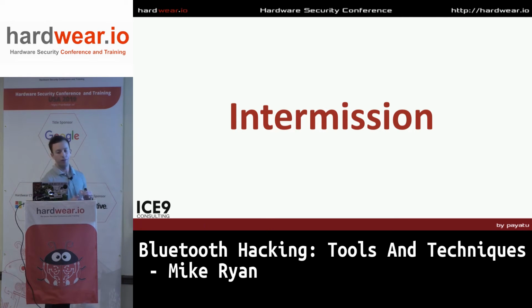What have we seen so far? First, reading data going to and from Bluetooth is straightforward. Really, it's simple. You turn on the HCI logging in Android, you do stuff in your app, you pull the data in, and Wireshark can interpret the data for you. And if you run up against limits in Wireshark, you can export the data and parse it in your favorite programming language. Number two, no encryption on the first two devices.